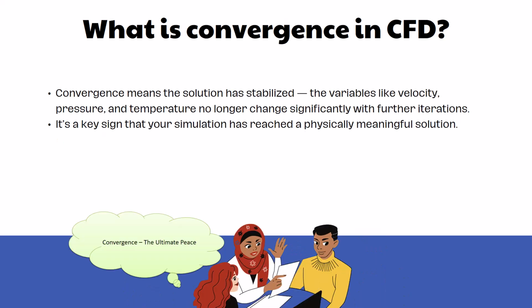So now, what is convergence in CFD? So convergence means that whenever your solution is getting stabilized, okay, you create one monitor point, suppose at an outlet. When you solve the CFD, at the start of iterations that parameter will vary much, it will go up and down, and afterwards at some point it will be constant. So there are 3 to 4 ways where we can say that my solution is converged or my solution is perfect now. For that you can use residuals, you can use monitor points, you can use mesh independence study, and etcetera. Okay.